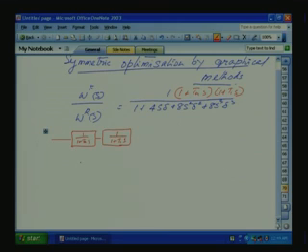And Tn we got as 4 delta. So, this also can be approximated with one time constant. Summing, we can take 1 by 1 plus Tn, where Tn is 4 delta plus T1. So, a filter with a time constant of 4 delta plus 1 omega r, we feed it and give it here. Then the effect of this one will be cancelled and the final transfer function will be like this, and we have found the response for this one using the computational method. Now, we will talk about symmetric optimization by graphical method.